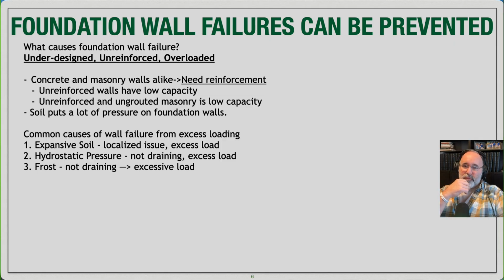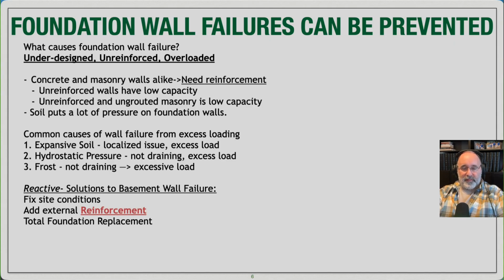So you have excessive load, frost, again, not draining and excessive load. All of those are just site conditions that should be able to be resolved by having proper site construction that gets water away from buildings, and any water that is near buildings can freely drain down to drain tile, and we get the water off of the design, off of the structure.